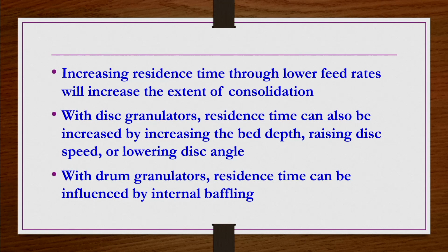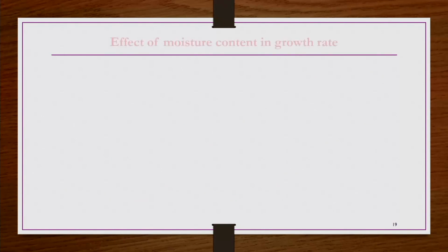Baffles are like those we generally have in mixers or continuous mixing equipment where a reaction may also take place. In order to enhance mixing we have baffles, and such baffles may be arranged inside the drum granulator. When you have these baffles in drum granulators, the residence time will again be increased.